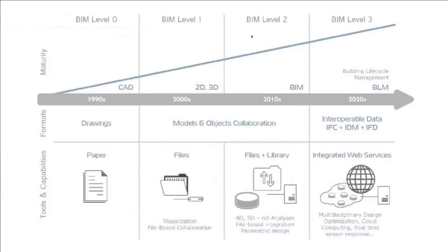So I'll jump to the next question. How does drafting details differ in the BIM workflow compared to the more traditional CAD workflow? Maybe you guys could touch on that briefly. I'll jump right in on that. It's both similar and dissimilar depending on the level of BIM that you want to use. We still use old two-dimensional details that were drafted in AutoCAD and converted to Vectorworks. And we place those in a very similar workflow as you would have in AutoCAD. I've yet to find a good reason to do a complicated BIM methodology for a typical concrete paving detail, for example. It's a pretty straightforward section cut.